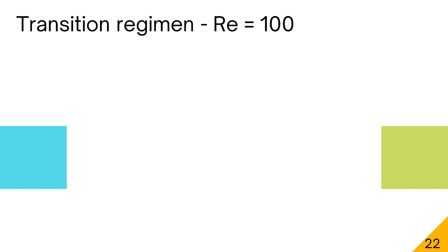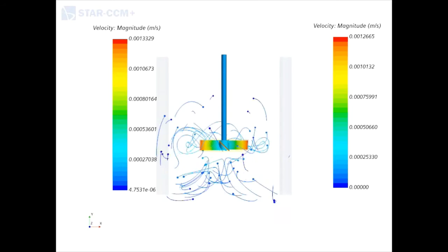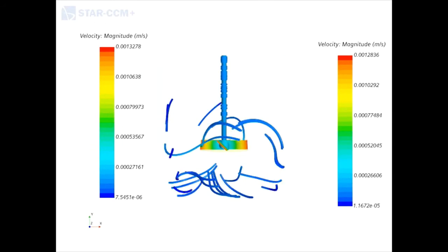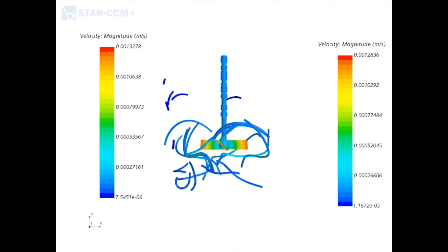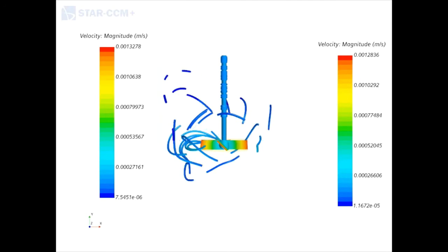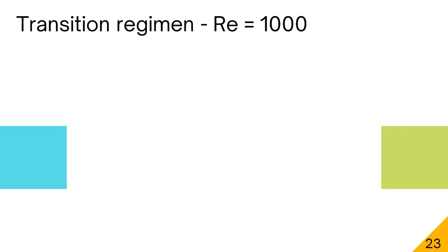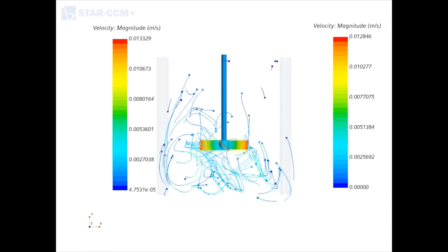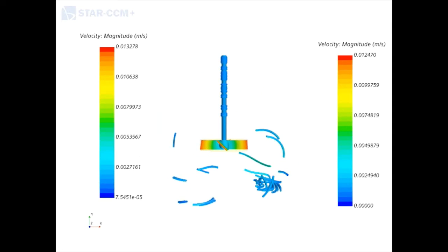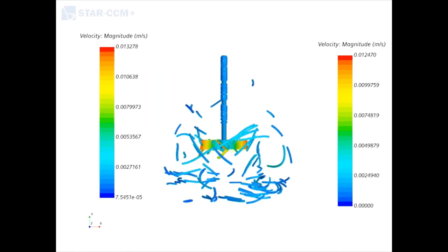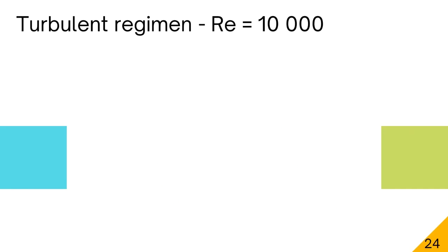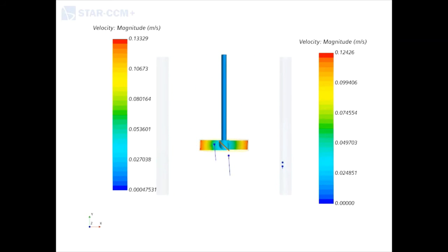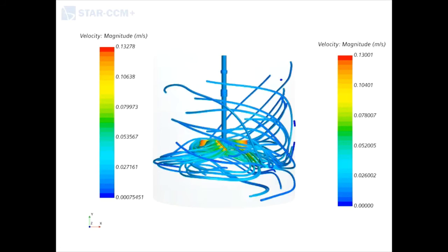When the axis is vertical and located in the center of the vessel, the tangential component of velocity is generally detrimental to the mix. Flow follows a circular path around the axis, which generates a vortex on the surface of the liquid that, due to the circulation in the laminar flow, gives rise to permanent stratification at different levels of unmixed substances. If solid particles are present in the fluid, circulatory currents tend to throw these particles against the wall of the tank due to centrifugal force, from where they fall, accumulating in the central part of the tank bottom. Therefore, instead of mixing, the opposite action takes place, that is concentration.